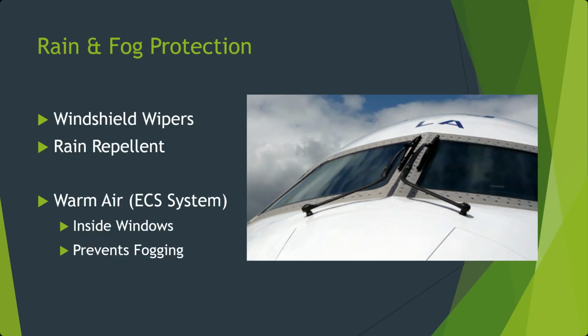So when we're testing them, if somebody's in the flight deck operating them, you have somebody on the outside of the aircraft, and usually we would just have a spray bottle of water or some other way to keep the windshield wet while we were testing them. You also want to make sure the windshield's fairly clean before you do this, because if you get any kind of dirt or rocks or pebbles caught and run them across the window, they can scratch the windows up.